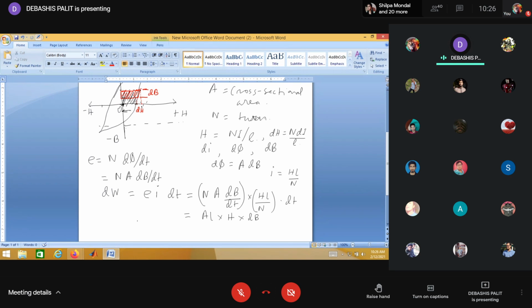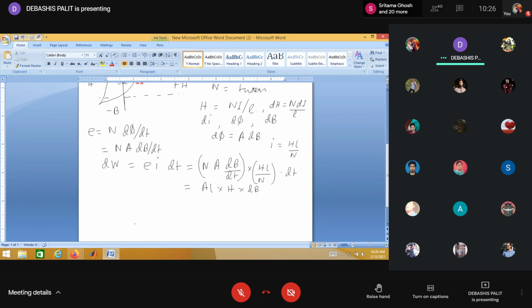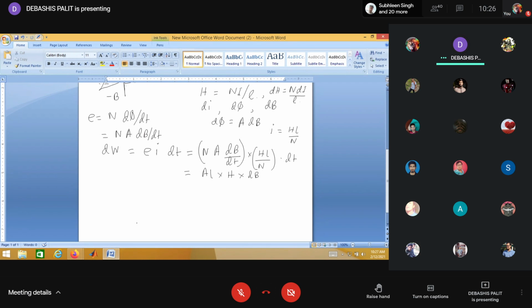for one complete cycle of magnetization, actually magnetization means the current reversal and flux reversal. Current reversal means the current direction changes from the initial moment. So if the current is plus I and then it is reversed, that is minus I, the flux changes from plus phi to minus phi. So this current reversal is taking place. So for a complete cycle, whenever an alternating voltage is applied, you have to consider one cycle of reversal.